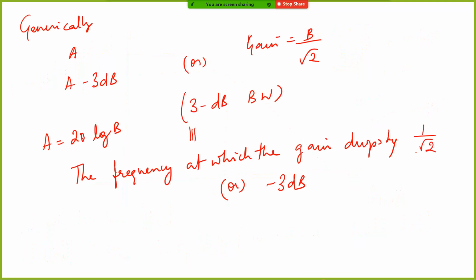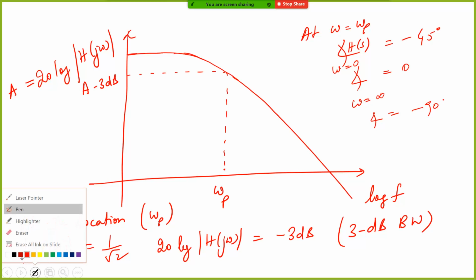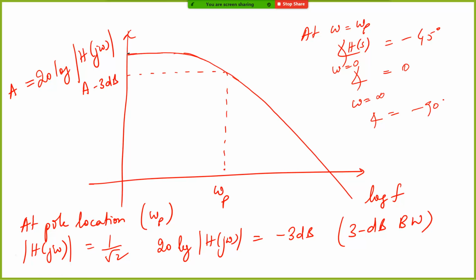Okay. So in order to easily understand these things, what is called the Bode approximation is used. The Bode approximation works something like this. Basically, I will just draw a straight line from here. I'm going to approximate these curves by straight lines. So if you take the x-axis as log f, this becomes a straight line at this portion. So you just extend this straight line, and you will see that it meets at the 3 dB frequency.